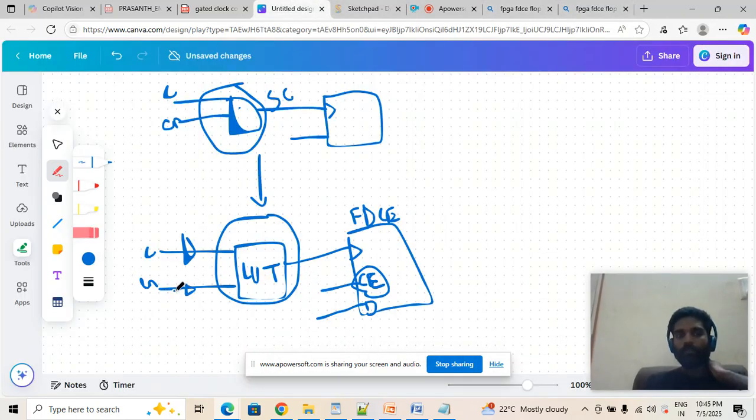We have to move the gating logic into the clock enable and let the clock connect directly here, right? So the clock and the clock enable will act as the clock gating in this environment. Now, how do we do this in the tool? As I already told, I don't want to touch my ASIC RTL for this reason, so the only option is to deal with the tool.